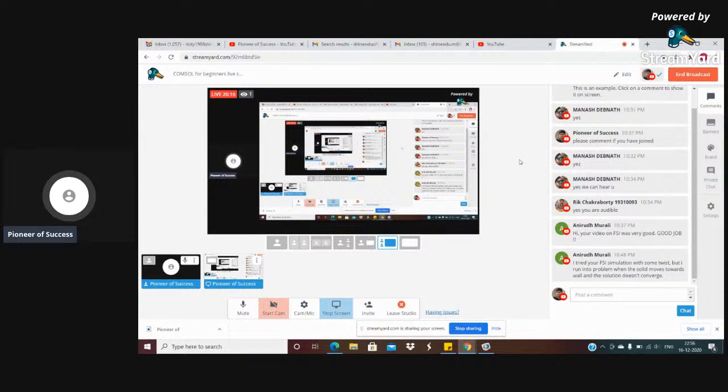Somebody commented, your video on FSI was very good. Good job. Thank you. I tried your FSI simulation with some twist, but I ran into a problem when the solid moves towards the wall. The solution does not converge. Maybe the velocity of the object which is moving might be very high. That is not compatible with the solution. I mean, that is not feasible. That's why maybe these things do not work. So you can try with other possible velocities of your object. It may work.